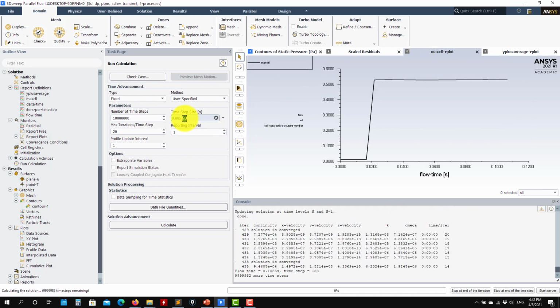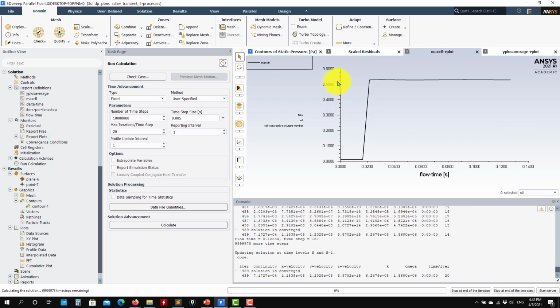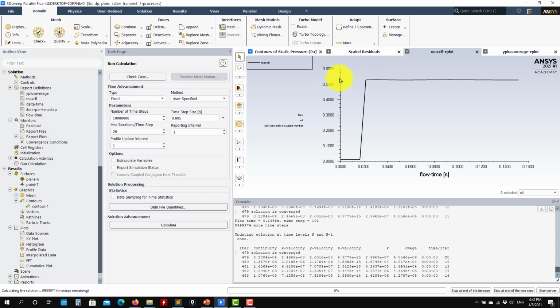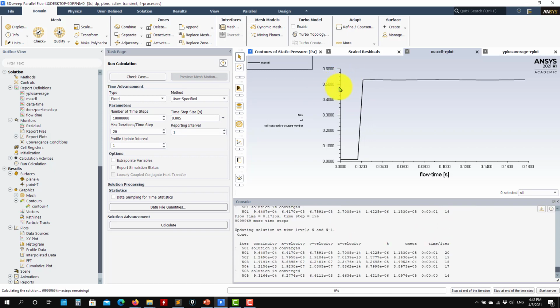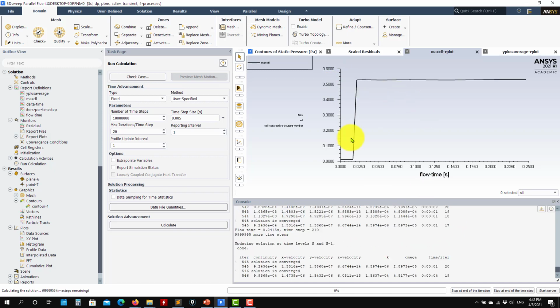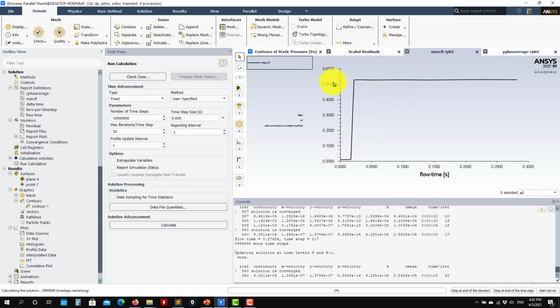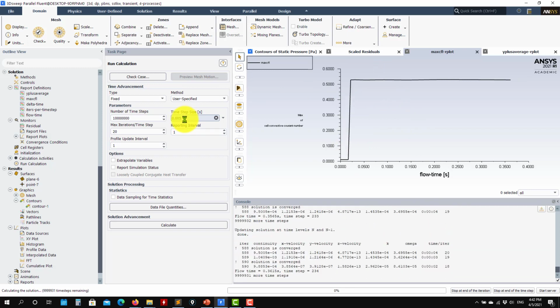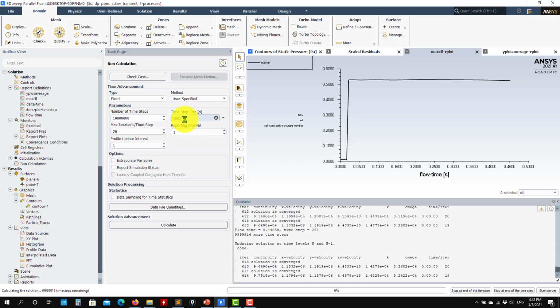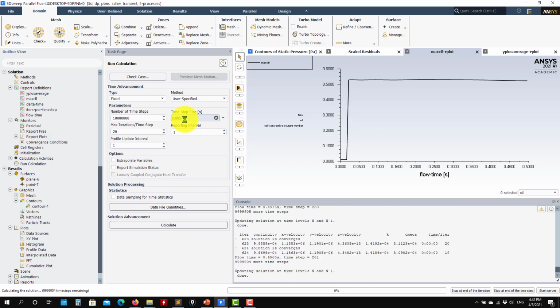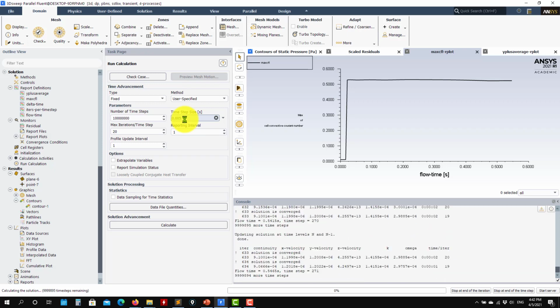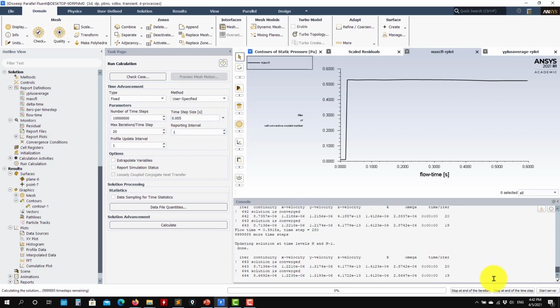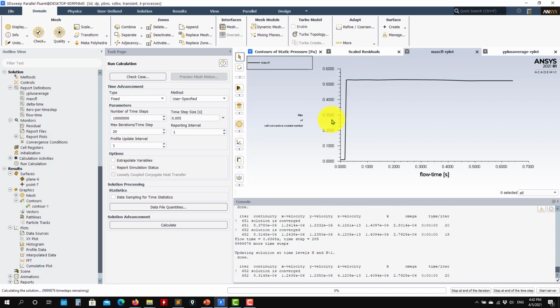But see that with a time step of 0.005, your CFL goes to something about 0.5. And see that here it is converging in 4 iterations. So see that from this to this, basically you are accelerating your convergence by a factor of 5. Okay, so this is what is important. We want to go with a large time step because we want to converge fast to get to the final time that we are aiming for. Okay, so see that I can still increase my CFL number.